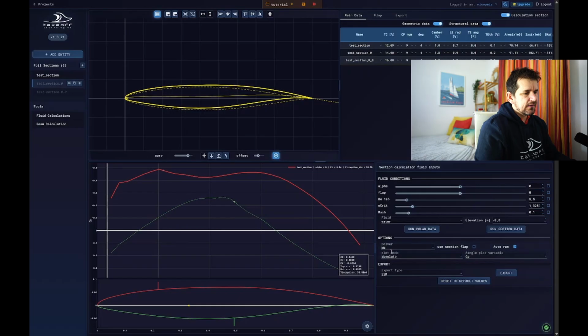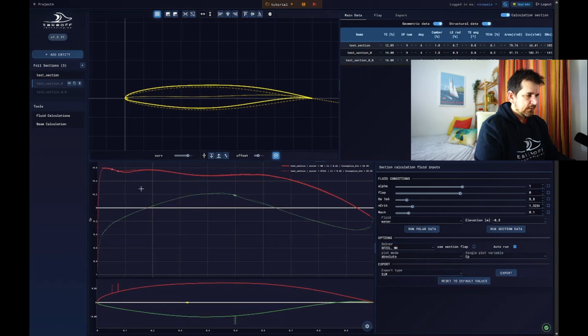This neural network has been trained with some points over the chord, and if here we want more details, we could run Airfoil. So here we have the comparison between the CPs, the solid line from the neural network, and the CPs from Airfoil, which are these ones. For the first 2% of the chord we're missing some values, but for the rest you see how well it matches, and that's the transition of the two different models, which match pretty well.